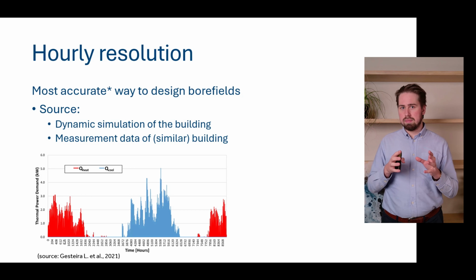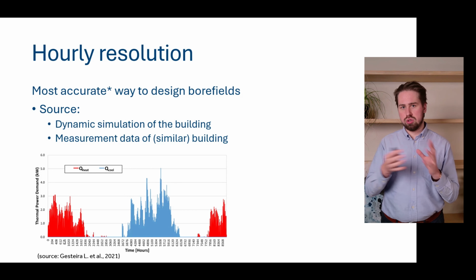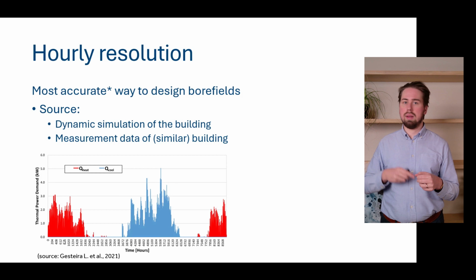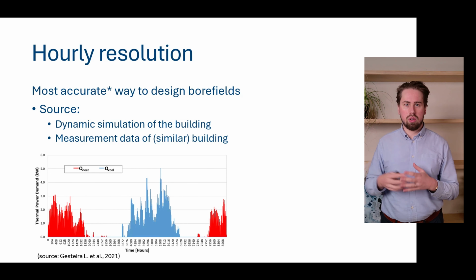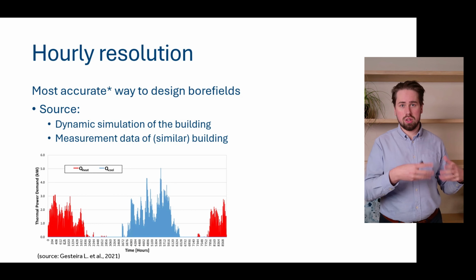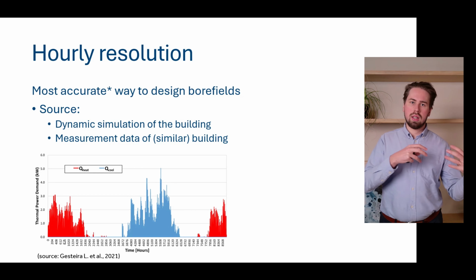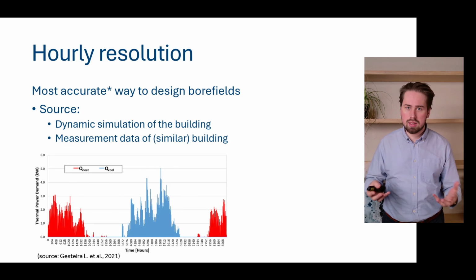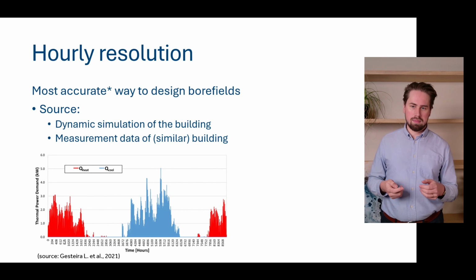It's also really helpful because if you do an hourly simulation, you see way better how the ground reacts, and you can also make design choices based on that. So you can put solar shading or perhaps put some different glazing in order to make sure that your loads are giving you the best geothermal design it can be. So the interaction between building design software and geothermal design is really interesting. And also when we go to more advanced methods, this hourly resolution will give us way more insight into that.